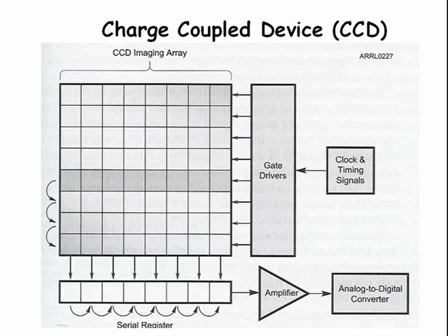A charge-coupled device is a type of integrated circuit that combines analog and digital signal handling abilities. The CCD is made from a string of small capacitors. The first capacitor in the string stores a sample of the input voltage and then passes the sampled signal onto the next capacitor when clocked. With each successive control pulse, the input sample is passed along to the next capacitor in the string.